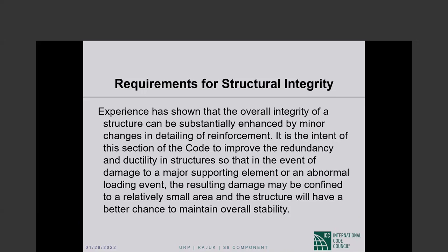Free end length is not something I understand. There is no free end. The upper part of the dowel is lapped with the upper column bars, and the lower part of the dowel is lapped with the lower column bars. Right.